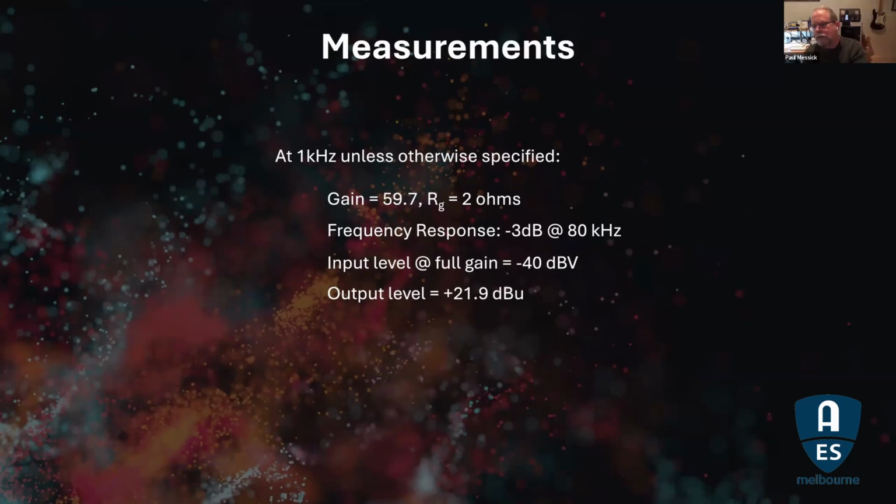And as I say, we're sort of addicted to A-weighting because when you're going to measure something and put the specs on a data sheet, or put it on the website, here's how great our product is, everyone else has been doing A-weighting, and so you're sort of forced to do A-weighting too. And the chips you're buying are spec'd with the filters built into that, and so on.